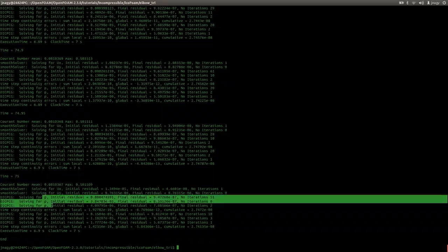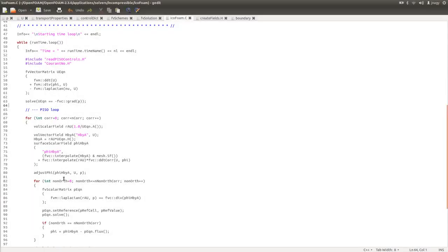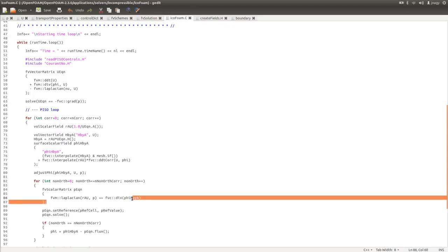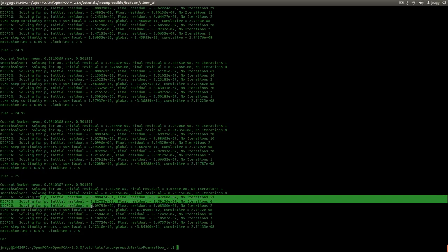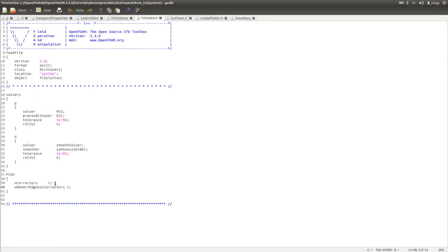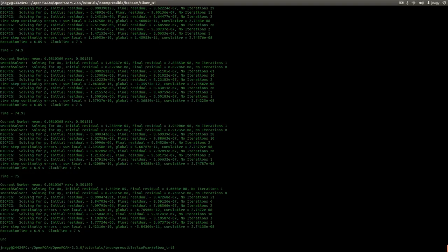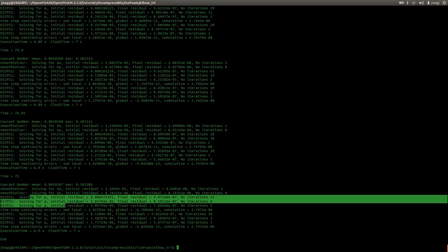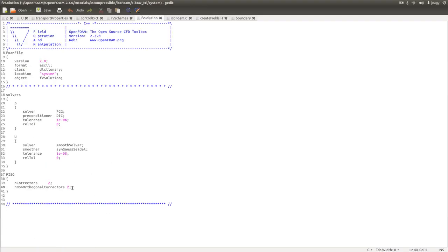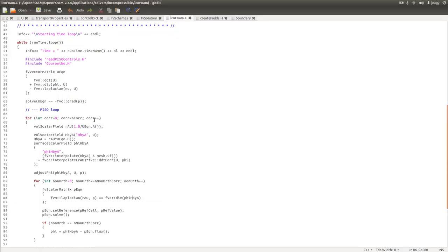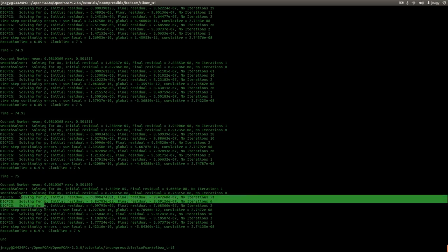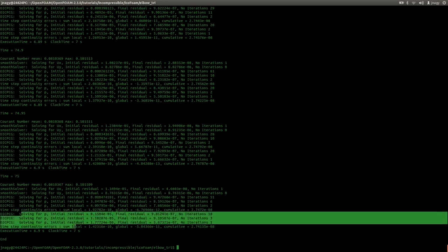And then we are entering the outer loop and the inner loop, and then we are making 3 iterations. Here we set for the inner loop 2 iterations, and I told you that we are doing 2 iterations, but actually I was wrong. We are doing 3 because you always do at least 1 iteration, and this number is the number of additional iterations. And this is then the actual number of outer iterations. And you see the first outer iteration and the second outer iteration.